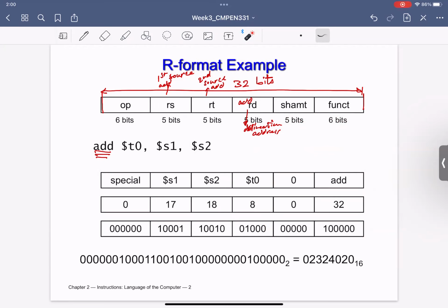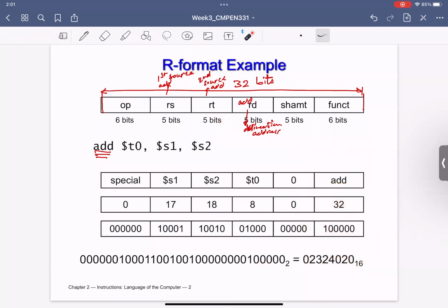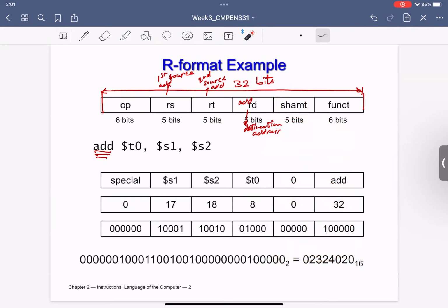Could this number change if the problem that you are trying to solve changes? Yes. Suppose that you have 64 registers. Will those 5 bits be enough? Of course not. You need to think about what the minimum number would be. If this is 64 but this is 32, will this be enough as a shift amount? Yes, because this is 32. How about if this is 64? Will 5 bits be enough? No, and so on. So we can play with all of these kinds of things. However, if you understand the concept, then you will not fall into the trap.